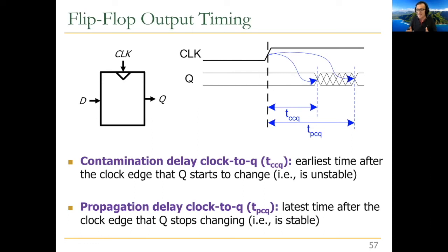And that delay needs to be added to your combinational delay to really get how long it takes for you to get the result out of a computational circuit starting from the clock rising edge. That's why this delay is extremely important. Again, that's true for the shortest signal as well, right? You need to know both the shortest path and the longest path, so that's why we need to know the shortest clock to Q and longest clock to Q delays.